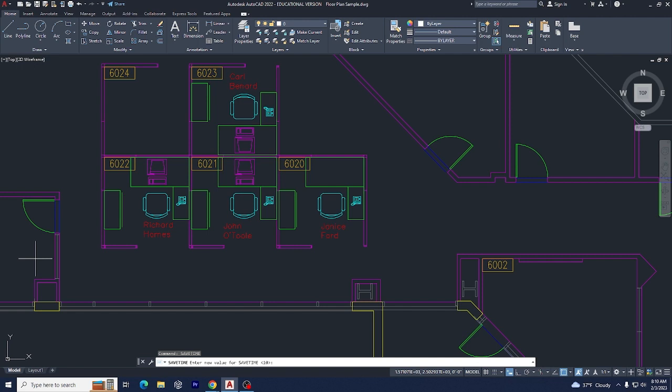To list the current settings for all system variables, use setvar. So let's try that. SETVAR. So you can enter the variable name, which we just looked at, savetime, so that's the variable name. It's set for 10, so that's just another way to do that, setvar, but you can do it for any variable, right? You can set anything with that you'd like.